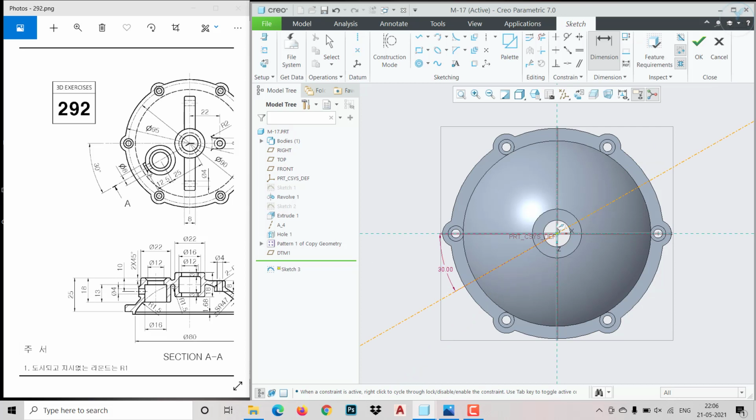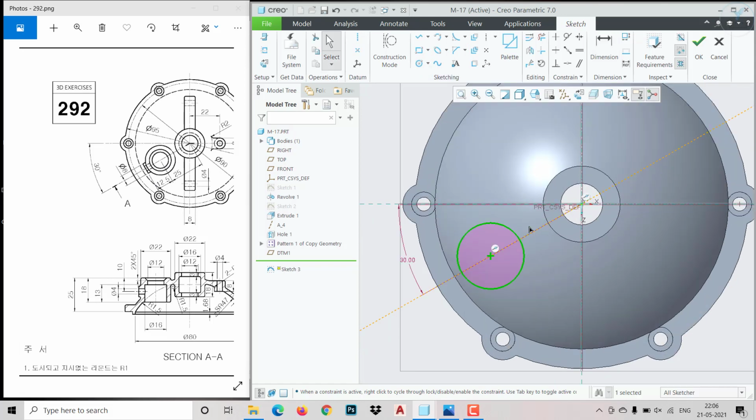And it is having a circle. So let me create a circle on that axis. So as you know, the outer one is dia 22. So give that one dia 22 and click on dimension. Click from here to here and then click on scroll. So it will show you that horizontal or vertical dimension only. You need to choose line. Okay.